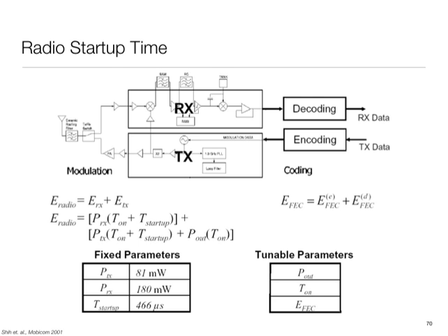And wake up, just like CPU, in radios has two components to it. One is the hardware takes some time to wake up. There are clocks and power supplies and stuff like that, and they take some time to come back up. And just like in case of CPUs, you had the operating system which needs to reboot. Likewise, in case of radios, from a cold start, you may have to become part of the network. So some synchronization with the network may need to happen, so that protocol overhead comes into play.